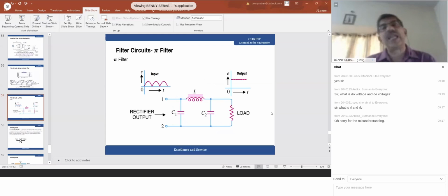So, the practical circuit. Along with that, one more resistance will be connected in parallel, which we call a bleeder resistor. You can put that idea in Google, bleeder resistor, because that is also there in all the power supplies. You check that one. It's for information. This circuit you will find in most power supplies, battery eliminators or adapters. When you purchase an adapter of 9 volt or 6 volt or 12 volt from the shop, or if you're constructing an adapter or a battery eliminator, this is a circuit we commonly use.